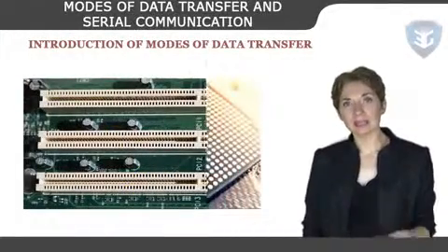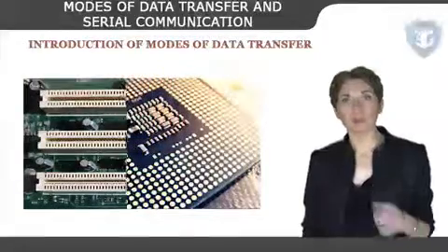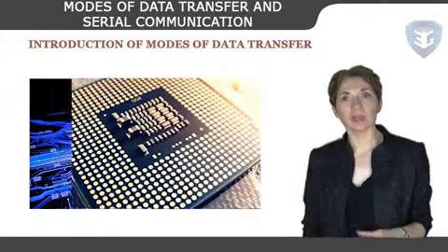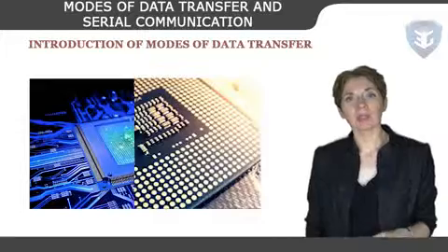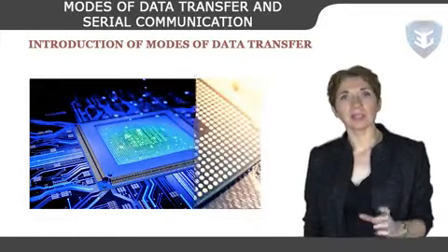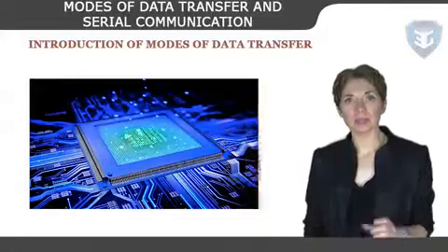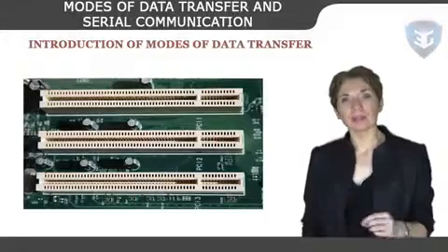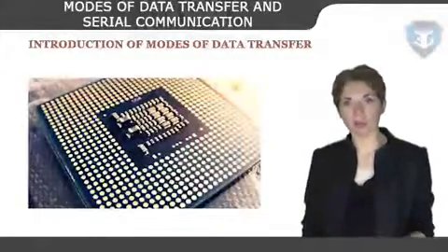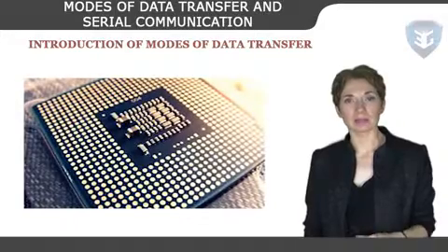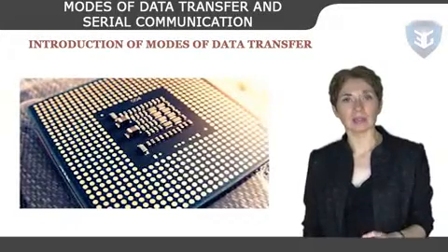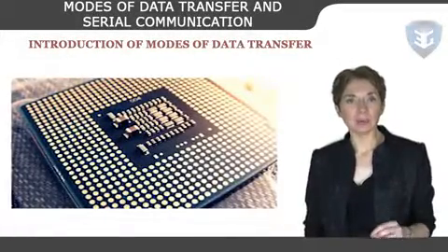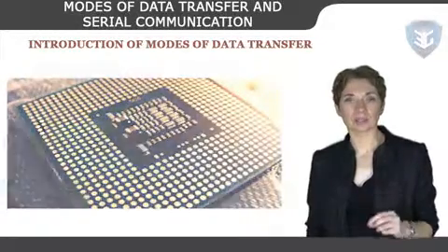One common method extensively used in microprocessors is to disable the buses through special control signals. Two control signals in the CPU facilitate the DMA transfer. The bus request, or BR input, is used by the DMA controller to request the CPU to relinquish control of the buses. When this input is active, the CPU terminates the execution of the current instruction and places the address bus, the data bus, and the read and write lines into a high impedance state that behaves like an open circuit, which means that the output is disconnected and does not have a logic significance.